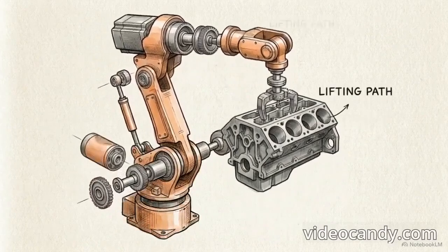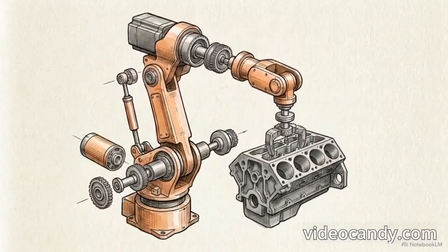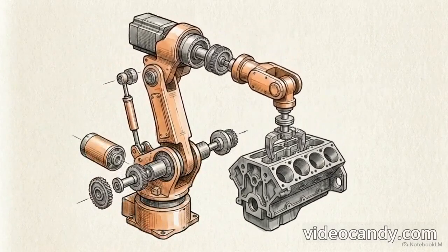When SMFC is applied, tracking remains stable, following the desired command with almost zero deviation. Data indicates the sliding mode component provides necessary gain to reject the torque load, while the fuzzy logic boundary layer ensures the motor's corrections remain smooth. This combination of rule-based interpolation and variable structure control addresses the chattering problem in robust systems. The result is a controller that achieves high tracking accuracy under disturbance without exceeding the mechanical stress limits of the servo hardware.